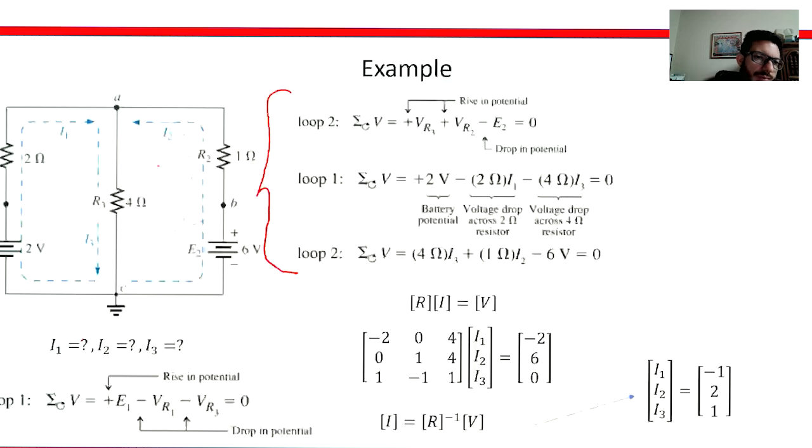And it's basically setting up an equation for each loop, always trying to keep the contacting elements as the coupling terms. So the only term that is in contact with this loop and that loop is resistor number 3. So if they're wanting to find three electric currents, I1, I2, and I3, we need 3 equations. So we're gonna find how to create those equations.